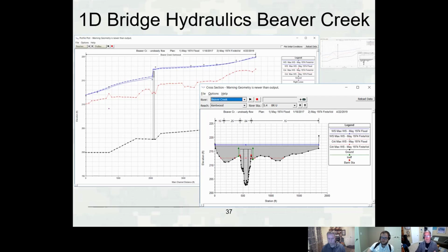Now that's not going to be true of every data set, because there's going to be a lot of data sets that were running slow because the 1D finite difference had to iterate a lot, especially at low flow or rapidly rises. Whereas the 1D finite volume might not have to iterate as much, so it might end up being faster. So it depends on the data set. But in general, if you had a very well-behaved model for both of them, the 1D finite difference is actually faster computationally than the 1D finite volume because of the reasons I talked about. That's the only drawback, as far as I'm concerned.